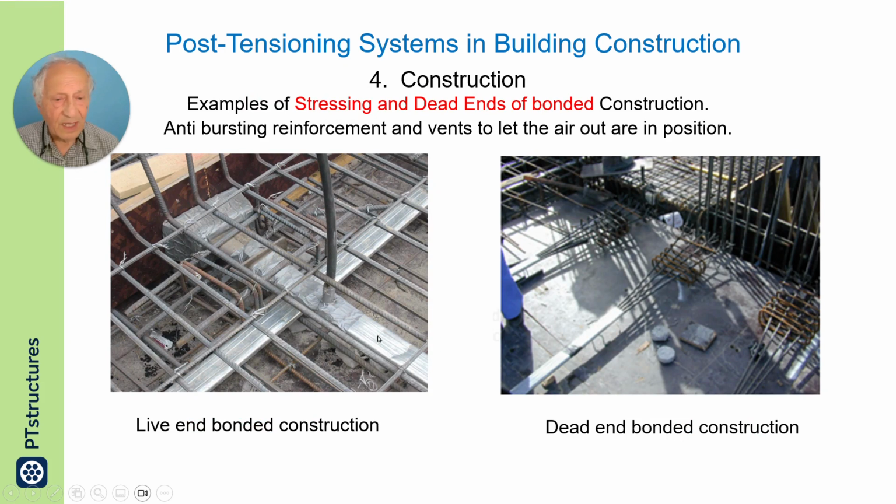At the left, I have the image of a stressing end of a bonded system ready to be stressed from the left beyond the bulkhead with the tube for receiving grout, and to the right it shows the dead end of the same system where the strands are out of the duct and will bond with the concrete when cast.